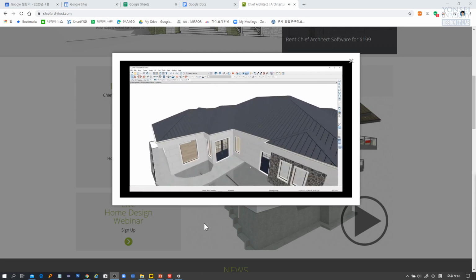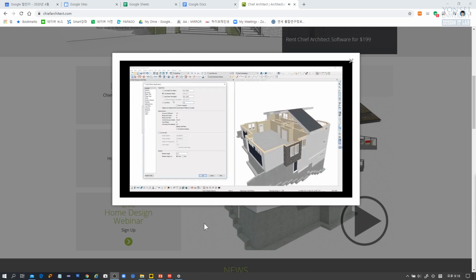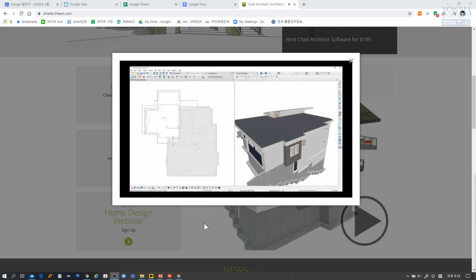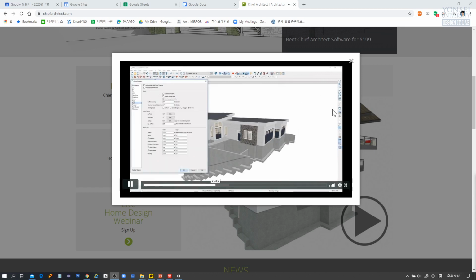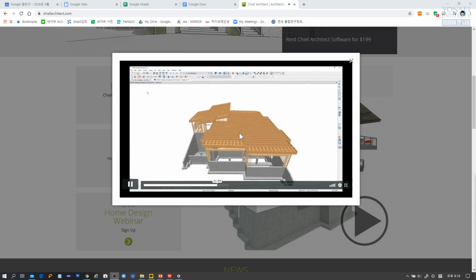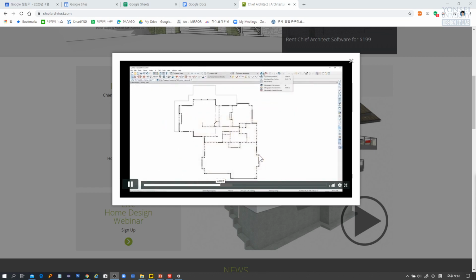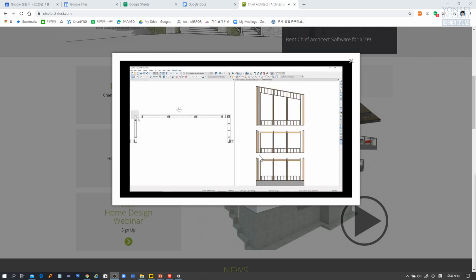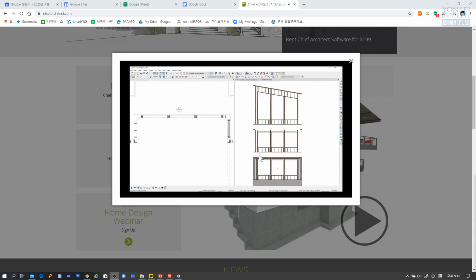Okay, the roof structure is simply selected and automatically modeled to cover the entire wall structure, and you can modify or model it piece by piece like this. The right side of this is a property viewer and 3D viewer, and some sketch mode. We saw this one, sketch mode in 2D. A 2D sketch directly affects the 3D model. Very detailed structural things in these mullion systems, framing systems.